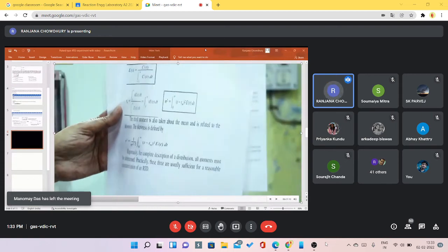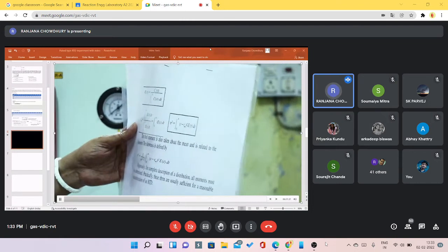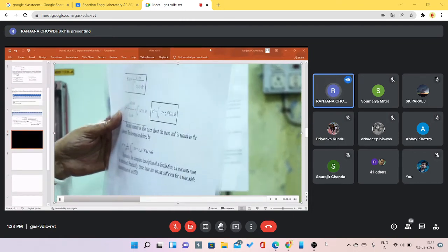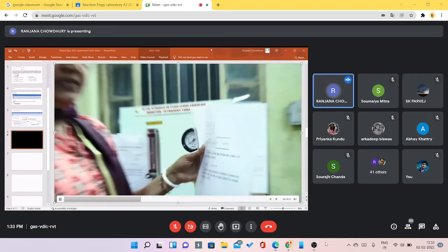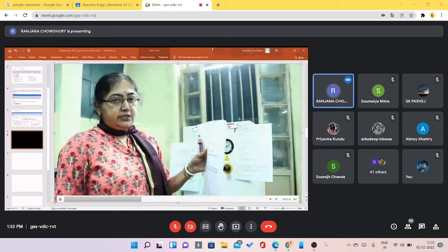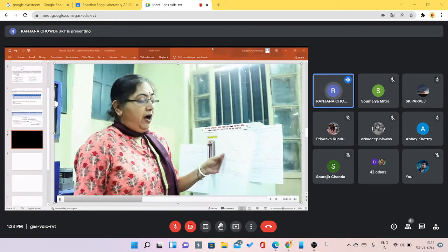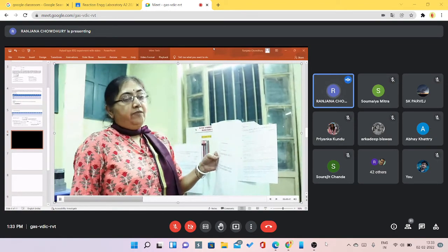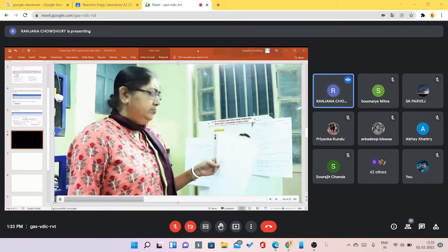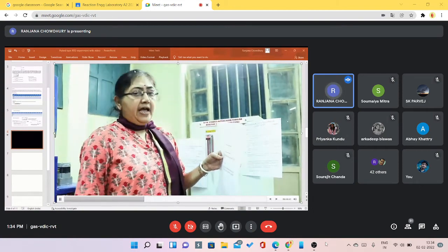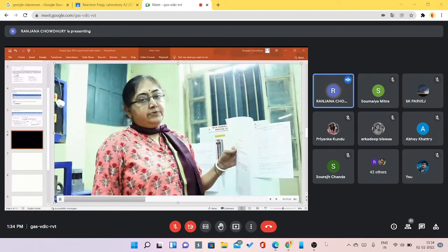Now, as soon as you determine E(t), you can also determine the moments of the RTD, or residence time distribution. The moments will give you the characteristics of the residence time distribution of the molecules in a reactor. The determination of moments is very important when you want to compare with ideal reactors, and also for reactors having different types of flow patterns. For the moments, you know that there are three types of moments.